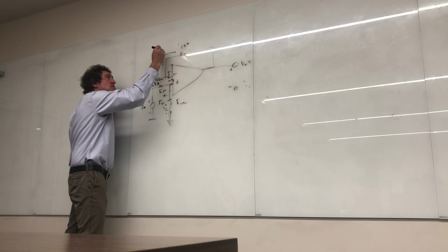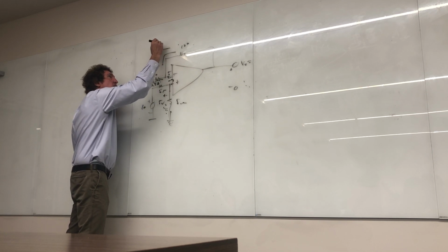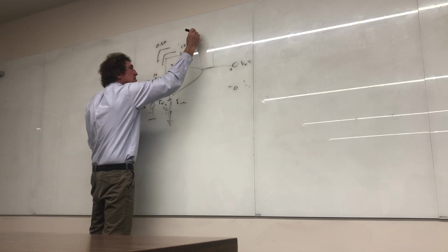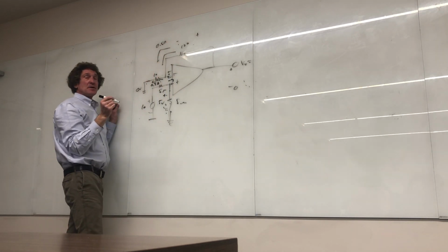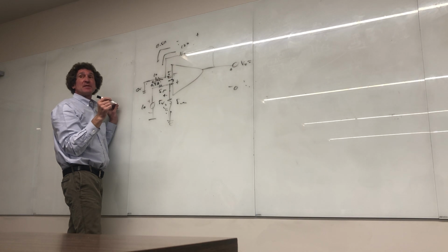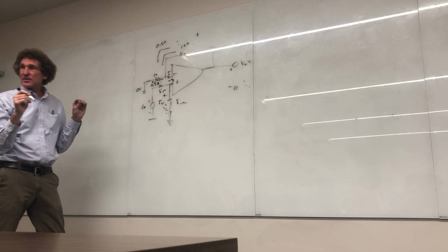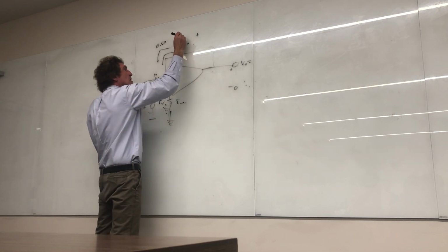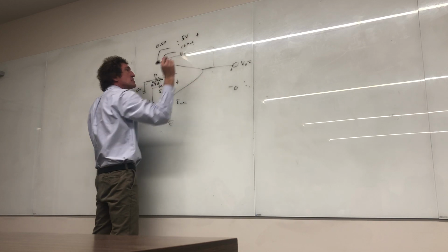All right, how much current's flowing here? 0.5 amps, right? What's the voltage across this? 100 divided by 2 is 50. Agreed, class? I'll stop for a second. Catch up with me. Gotta make sure. Does everybody see it? So that's 50 volts across that 100 ohm resistor.